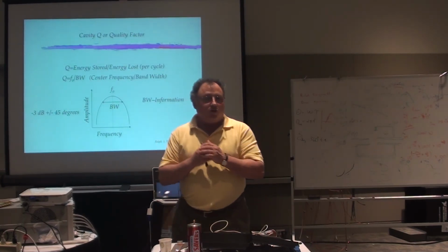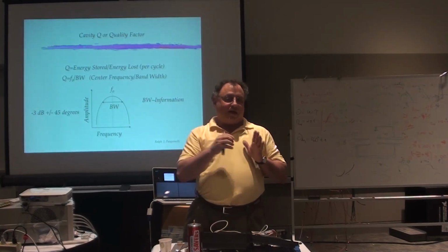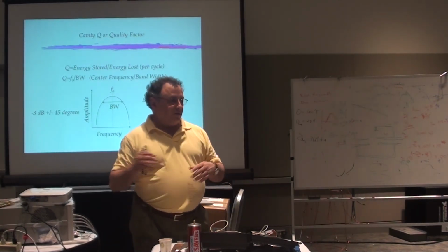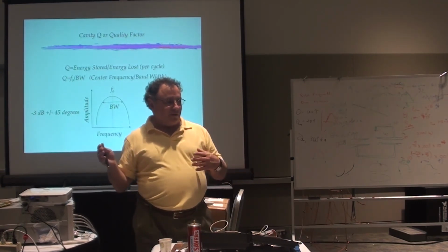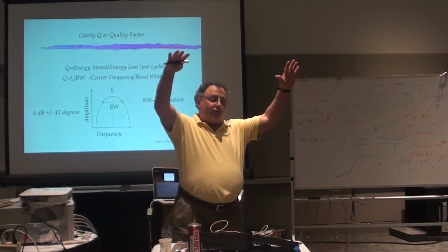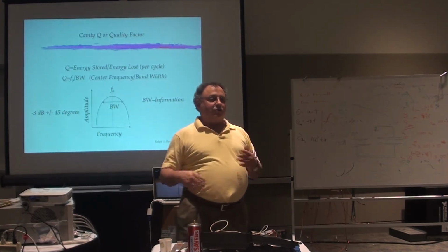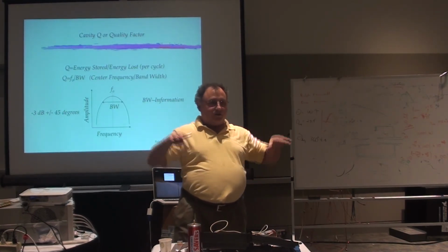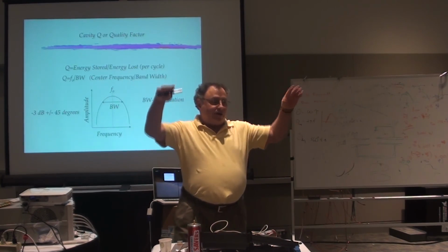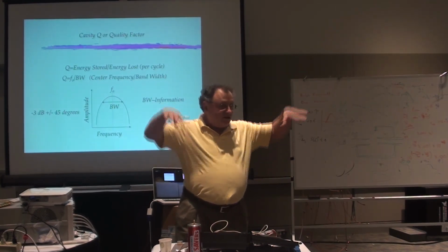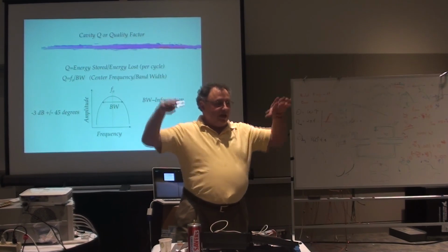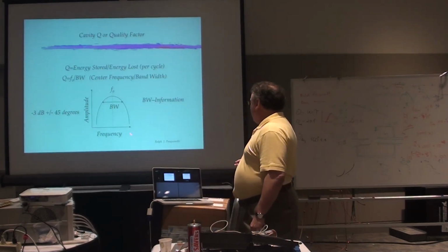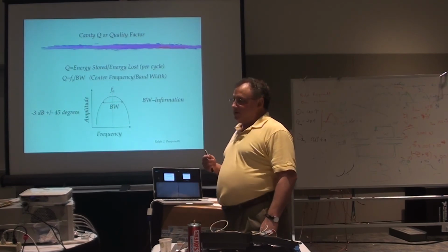It's also a good rule of thumb for simple cavities. When we were talking about noise, and when you guys were looking at the noise on the spectrum and seeing the noise floor go up and down, as you change the resolution bandwidth, your signal should have stayed perfectly fine, but the noise floor should have been going up and down. If you change the resolution bandwidth by a factor of 10, it should have changed by 10 dB, for instance. And that's because the real noise bandwidth of any system is the integral of whatever is underneath that passband.